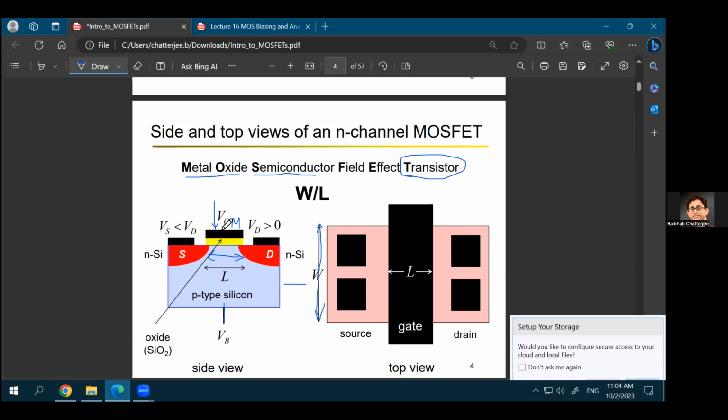So that comes back to your understanding of the op-amps, where we talked about the fact that there cannot be any current flow in the input terminal of the op-amp. Because the input terminal of the op-amp, as you'll see, eventually goes to the gate terminal of the MOSFET. So that's something we'll see when we discuss the internal structure of an op-amp.